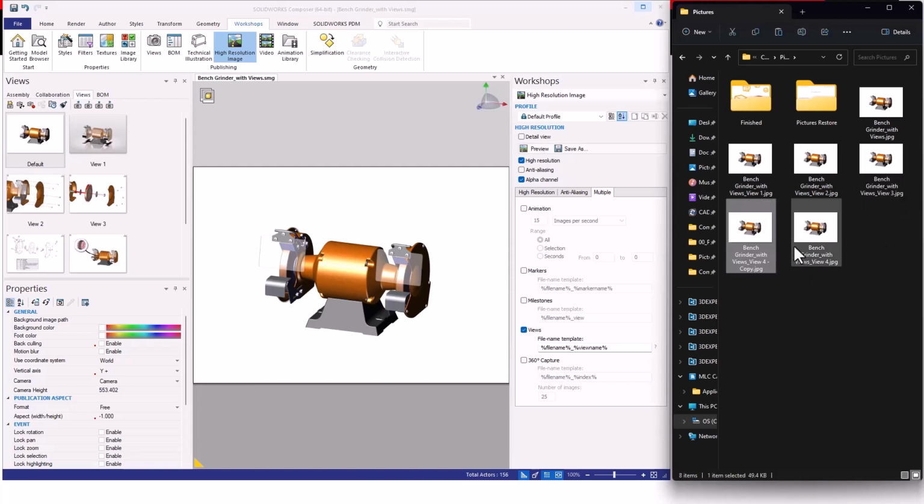This is a rather small project at the moment where we only have 6 views that we're worrying about. However, if you get into much larger projects where you have 100 or more views, you really want to have more meaningful names. That's something to keep in mind as you set up your project, because once you have created placeholders or you've actually exported your images out, you do not want to be renaming your views. That is not recommended because you're going to create a lot of extra work for yourself.